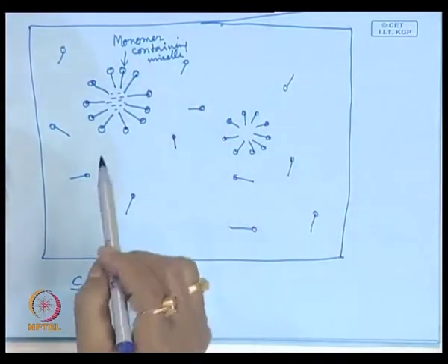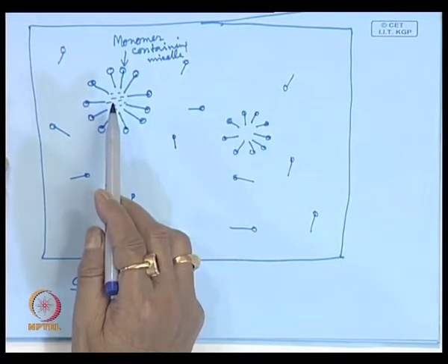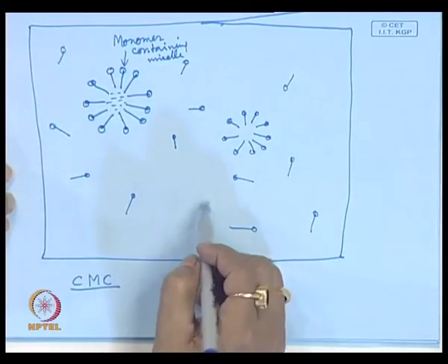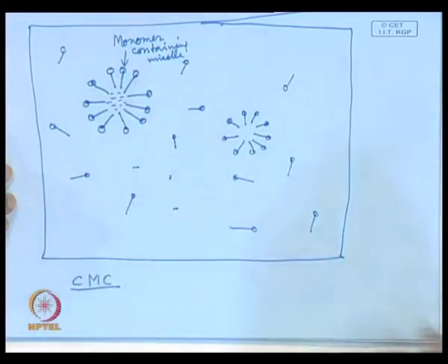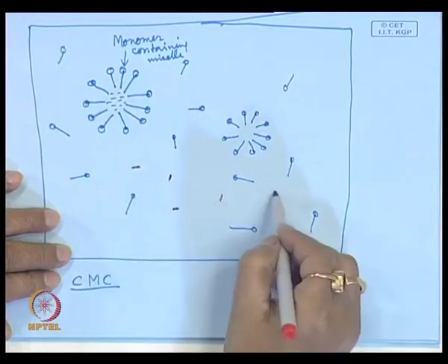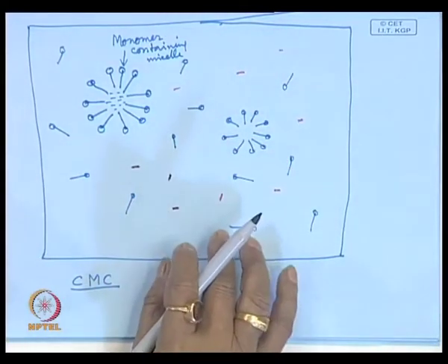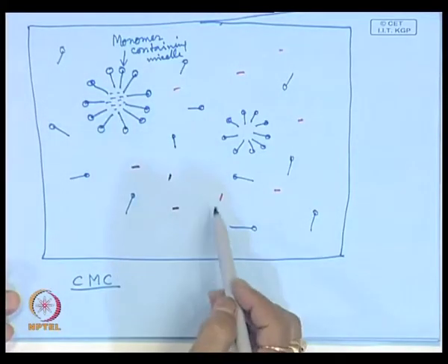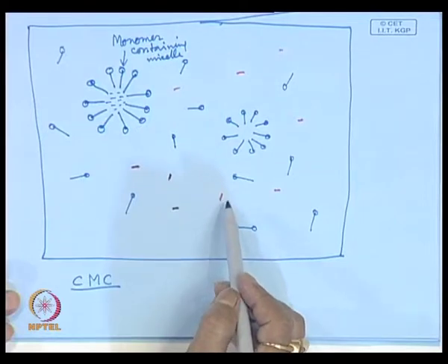So, in this polymerization system, what have we added? We have added soap or detergent and monomer, and some quantity of monomer, although very small, will remain in the aqueous phase. Suppose these are the monomer molecules, because although we say the monomers are hydrophobic organic, they have certain limited solubility. That solubility may be 1% or less than 1%, or it can be more than 1%, 2 to 3% or 4% solubility of monomer in aqueous phase. So, after adding monomer, we will get monomer in two phases: in the organic phase within the micelle, and in the aqueous phase in dissolved condition. Understand?